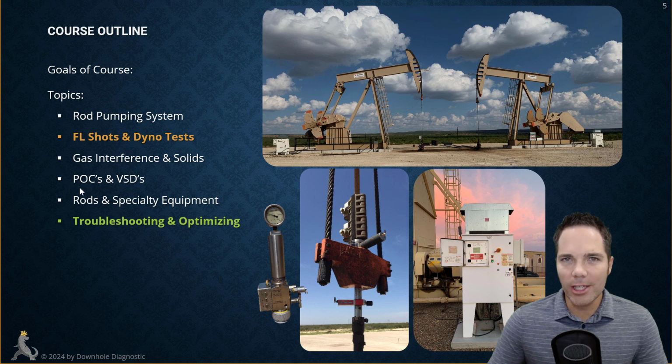We're going to look at automation, a pump-off controller. That's what this is right here, and it's integrated into a variable speed drive. So if you just have a pump-off controller, it will shut the well down if the pump fillage drops. If you integrate that with a variable speed drive, then you can slow the strokes per minute down if the pump fillage drops. But this is automation that's reacting based on what the dynamometer cards look like.